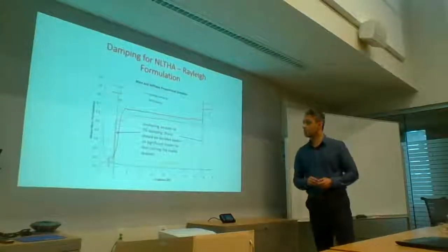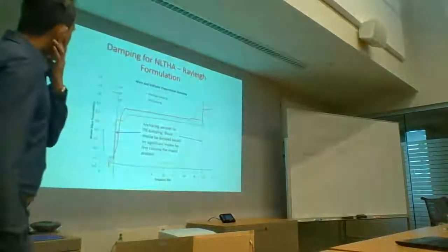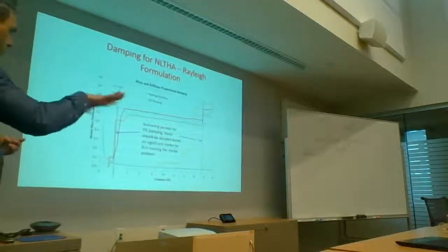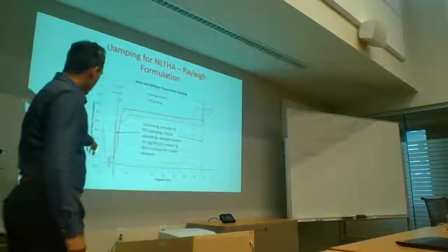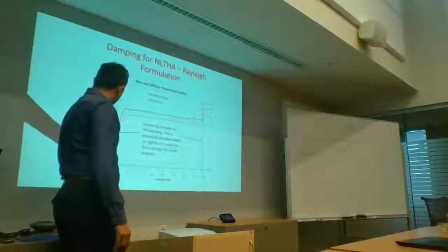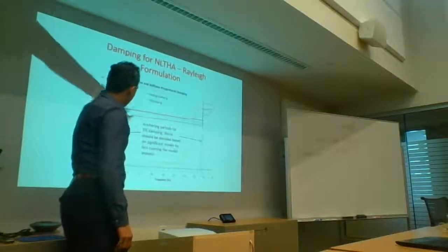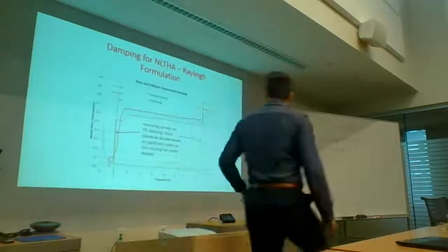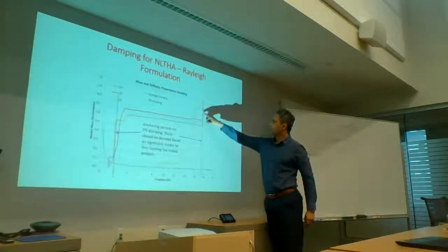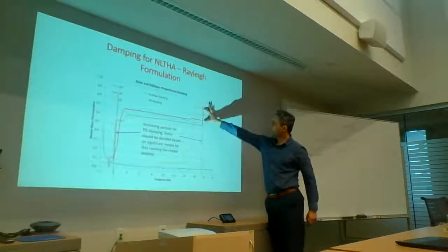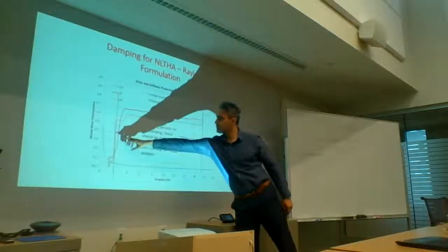So this is one actual project that we worked on, and you can see here the UX and the UYs are the two horizontal directions, and this is the modal participation graph. There is a big mode kicking in here. There's a small mode here, but then this is a big mode. There's a little bit here, and then this over here is a big mode. So we're anchoring to this mode, and these two modes from the two directions are quite close, so we're anchoring here.